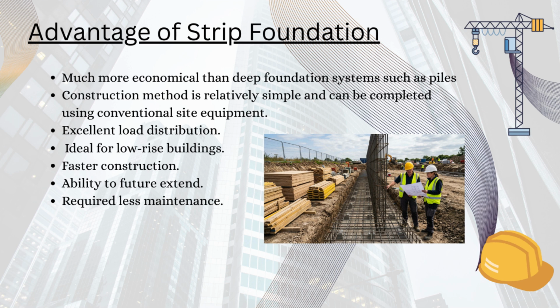Third, they provide excellent load distribution, spreading the structural load continuously along the entire length of the wall or row of columns. They are ideal for low-rise buildings, where the structural loads are moderate and the soil has good bearing capacity. Construction is also faster because excavation, reinforcement fixing, formwork, and concreting can be carried out continuously along the trench.